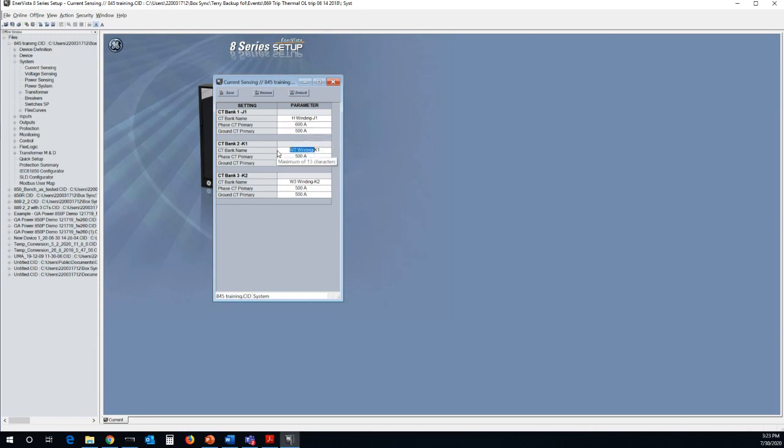My next winding, I'm going to set that as the X winding. Wire that to K1. And remember that one had a 4,000 to 5 CT ratio. Uh-oh, I did something wrong. Oh, I entered the wrong value. I tried to set that at 20,000. I've never seen a 20,000 amp CT ratio, but that should be 4,000, right? All right. Now the ground CT, the primary, is 400. So I'm going to set that to 400.